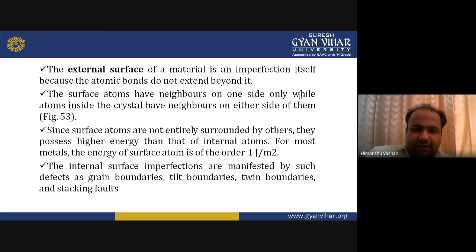The surface atoms have higher energy than internal atoms. The internal surface imperfections are manifested by such defects as grain boundaries, tilt boundaries, twin boundaries, and stacking faults.